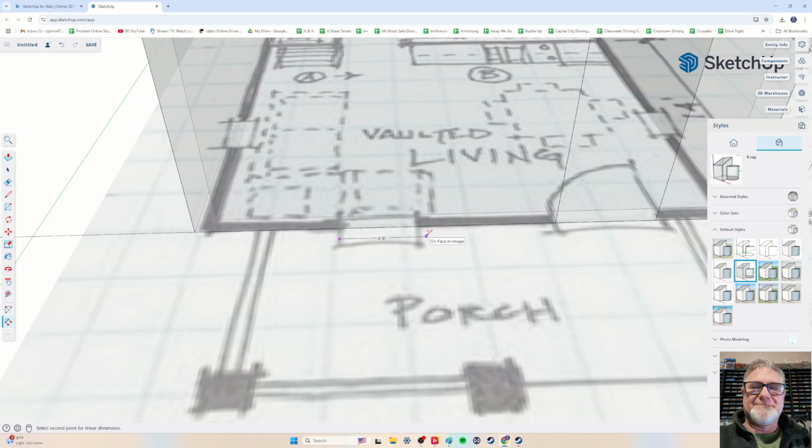So here we have a two. Let's say maybe it's 2.5 feet. It's actually not. Looks like it's about 2 foot 3 inches. So as long as you have a consistent two, okay. I'd love to go 2.5 feet, but it does not look like it really is. So I'm going to go 2 foot 4 inches. For me, it's a lot easier to figure out how many inches that is. So 2 feet is 24 inches plus 4 is 28. So I'm going to say these windows are 28 inches wide.